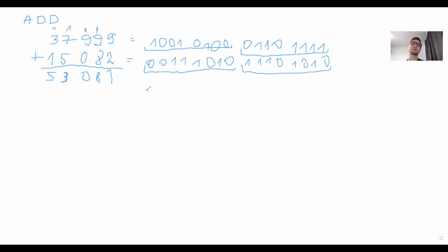You would probably guess that regardless of the size of the number, all we need to do is just add carry, bit A and bit B, and we can do it within all of this number, regardless of how many bits there are. And let's check it out. When we add two numbers, for the first bits we always assume that carry in is 0, right? The computer only has this 8-bit adder that accepts A, B, and carry in, so we need to give it some carry in initially. So when we add the bottom part of the 16-bit number first, we give carry in equal to 0.